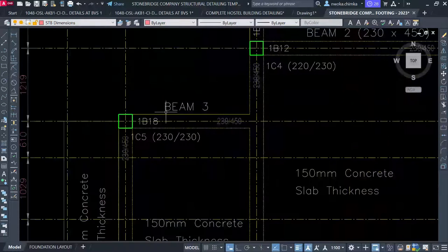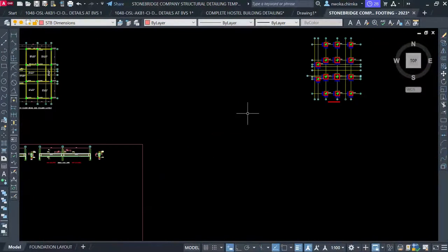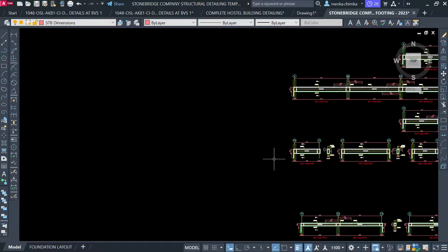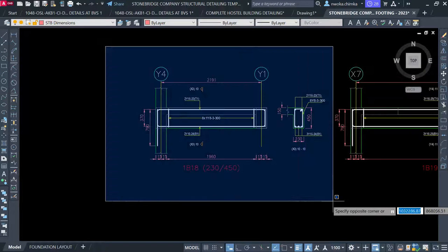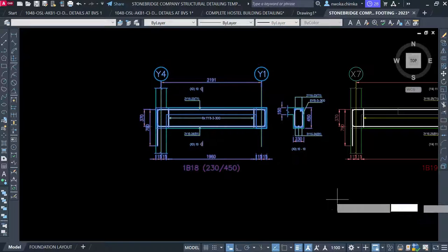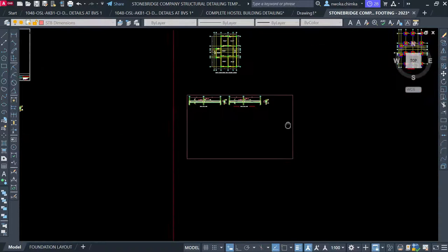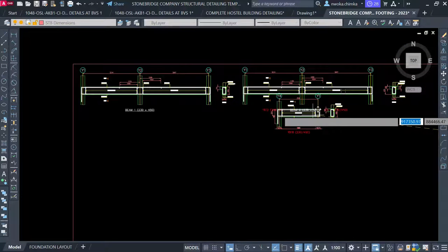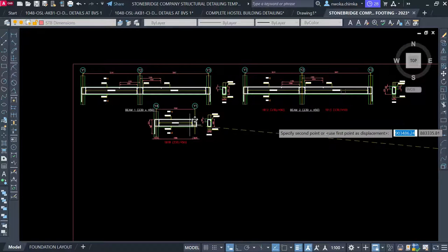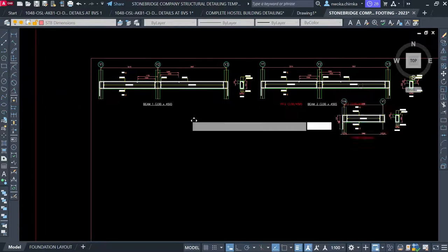So I'm going to locate beam 18 and then change it. I'll go and locate it right now from this place, beam 18. I'll just highlight it now, and move it, enter, from here to this place here. Always put your beams just in 2s, because that's what can be contained on the A3 paper size. Don't put 3 here, because it cannot contain them. So always put it 2 this way.